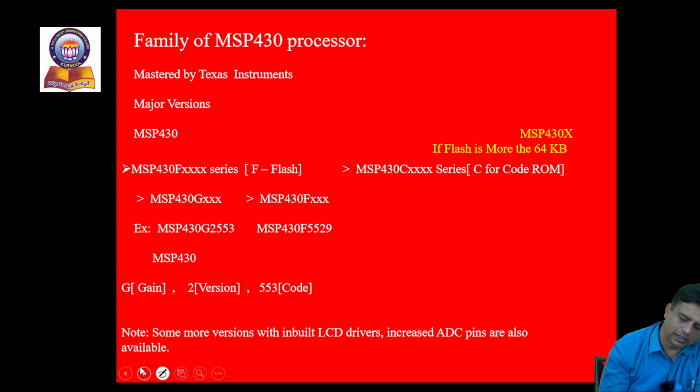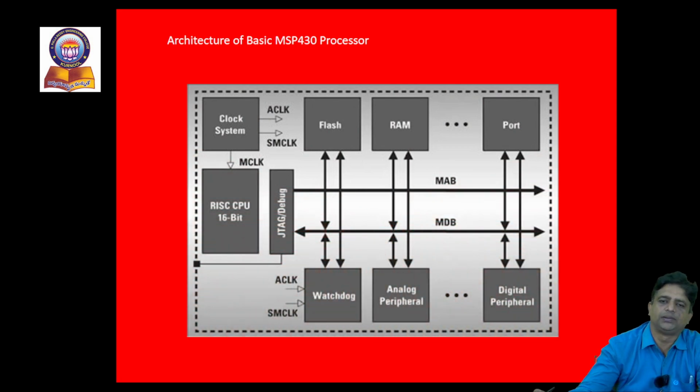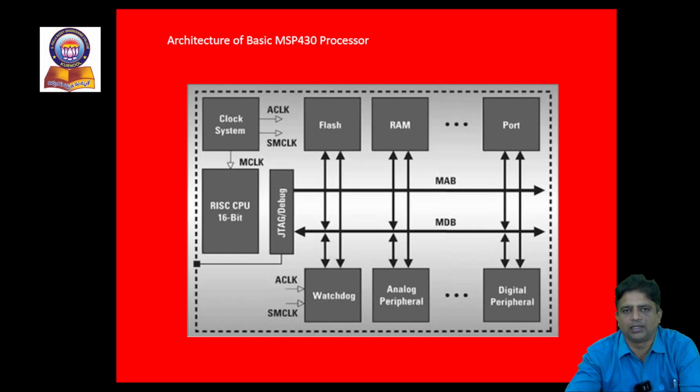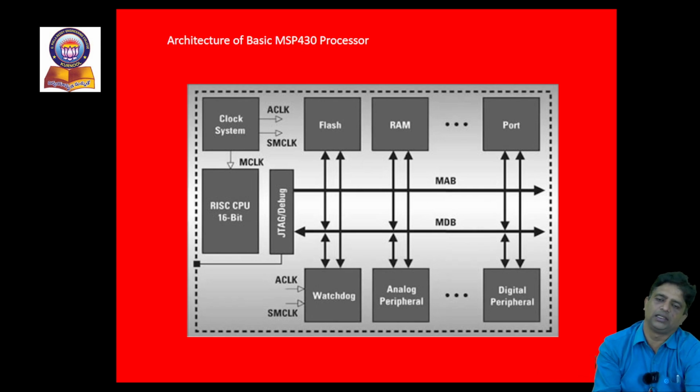In continuation, after the features, if we look over the block representation of the MSP430 processor, it has all the provisions that a general microcontroller architecture possesses. Now we can see a block diagram of the ALU. Whenever we start to learn about any architecture, it is preferred that we trace out where the ALU is inside the architecture of this microcontroller or microprocessor. On the left side of the architecture, we have a 16-bit CPU arrangement, considered to be the ALU brain of the CPU present in MSP430.